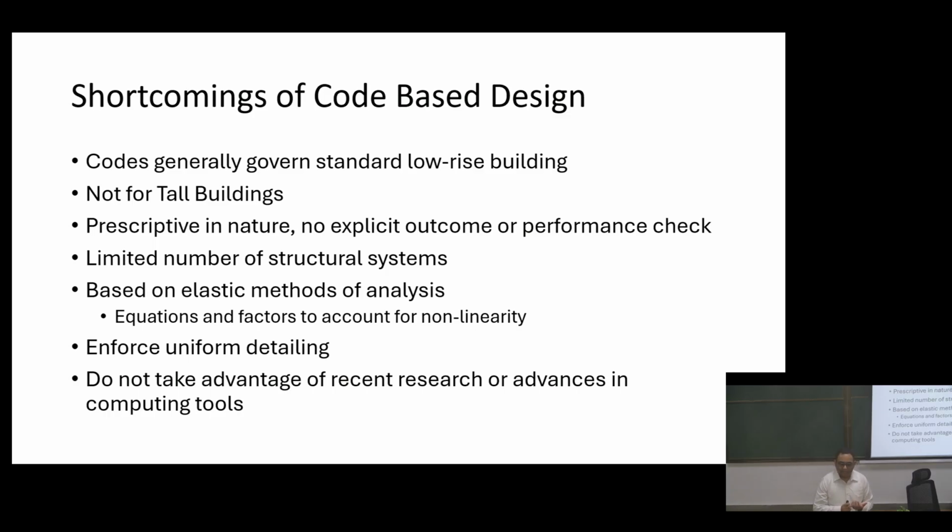Does everybody know what elastic method of analysis is? Yes. Can somebody explain? The stresses are below the elastic limits. Limited to the elastic. Stresses are below Hooke's law. So generally, we are trying to maintain that, right? And then detailing is again prescribed. So how much reinforcement, what's the area of steel, how much cover, everything is kind of prescribed in a sense.